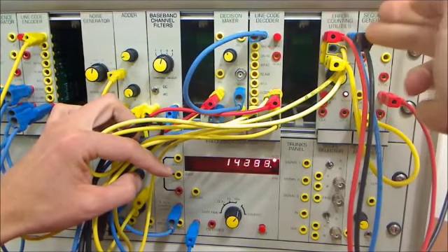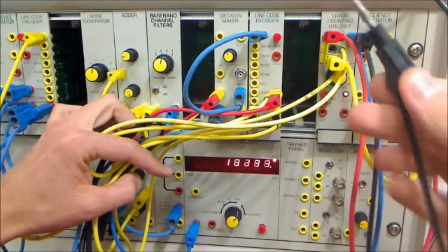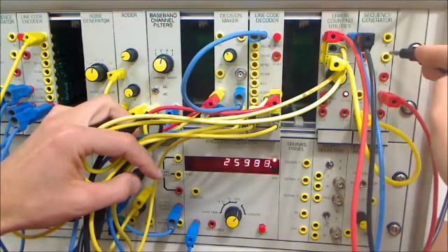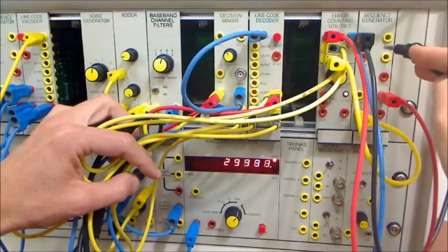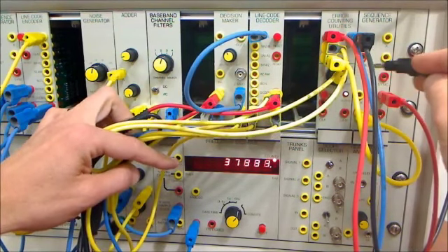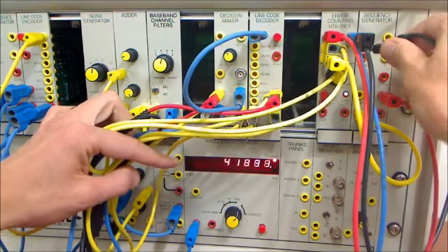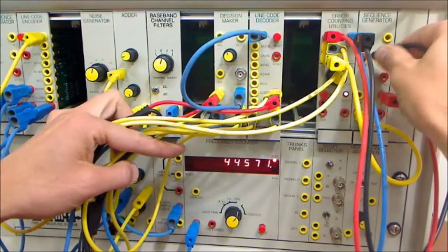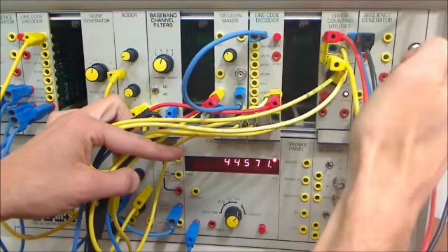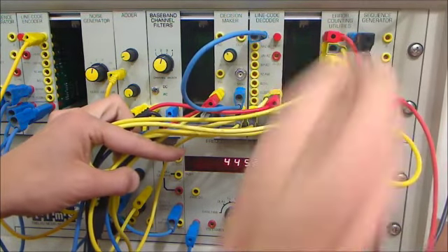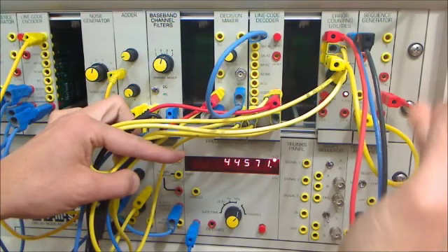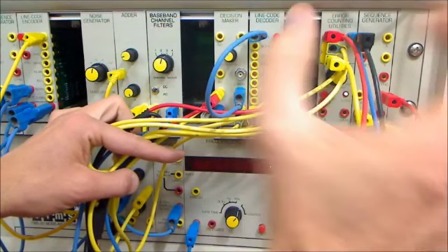We now take the same error pulse stream and on the black lead, we put this error stream into the sequence generator's reset input. It'll cause the local generator to slide, be a sliding window correlator, until it matches the received data stream. I'm about to connect to the reset pulse, and there you go. You can see the errors have stopped accumulating. There are no more errors, it's not incrementing, which basically means the recovered sequence with no errors is now exactly the same and aligned with the local sequence.